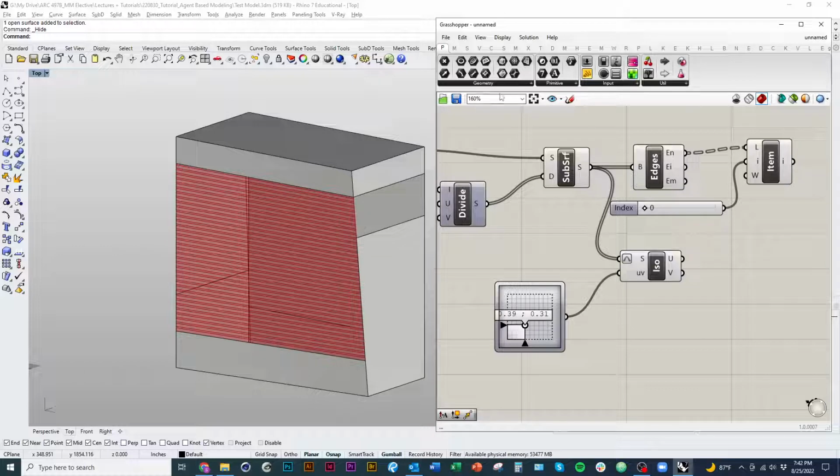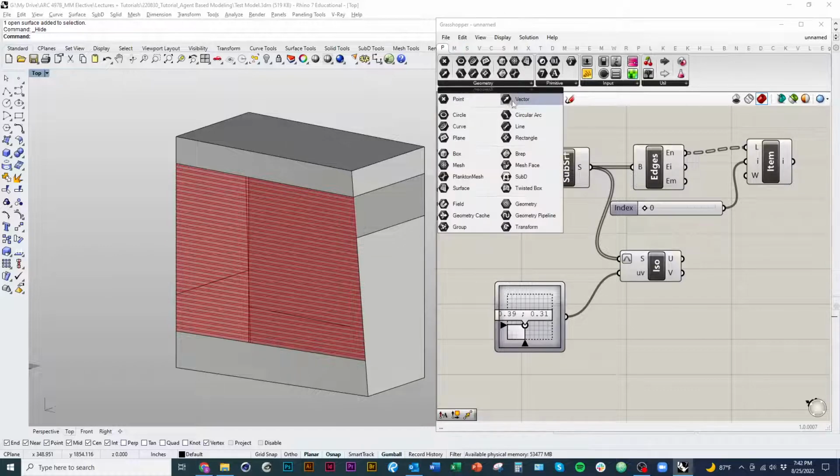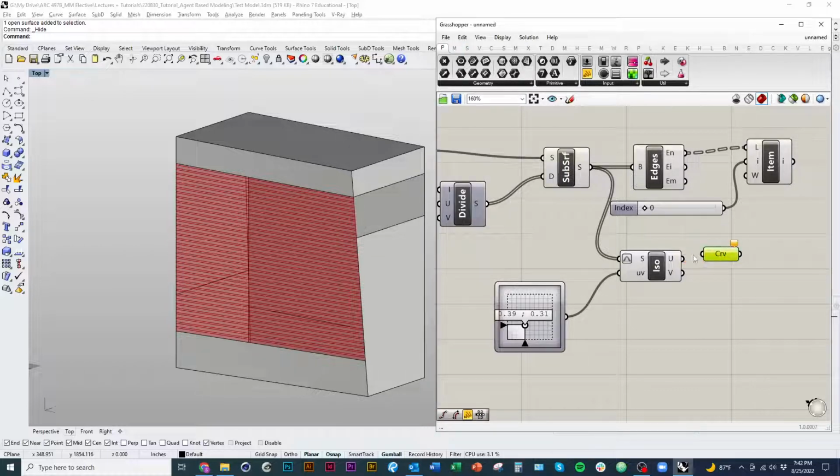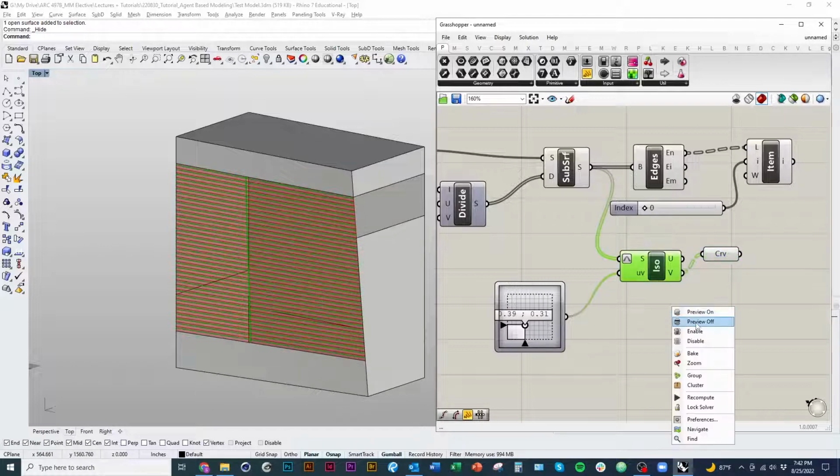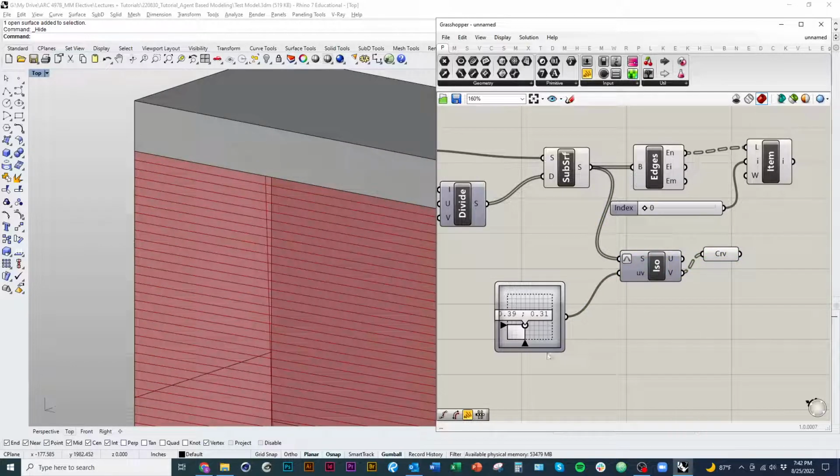And if I get the parameters, geometry, get a curve, it's giving me a curve in each direction. Obviously that's the U direction there, and then the V direction. We just need the V direction ones, but you can see that's giving us the curve in that direction.